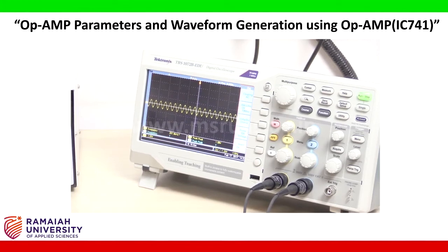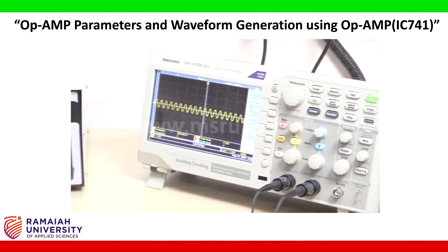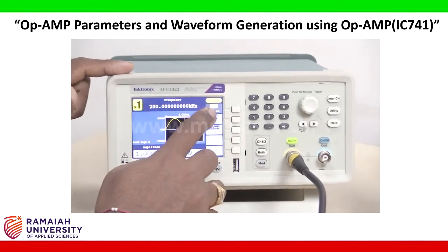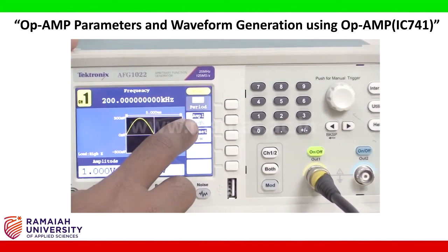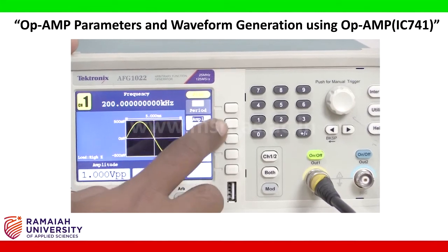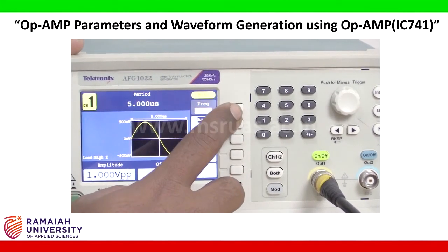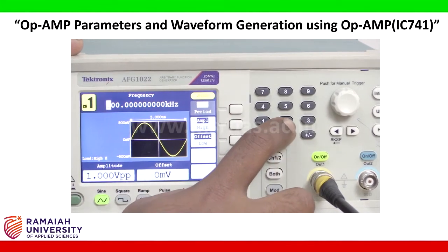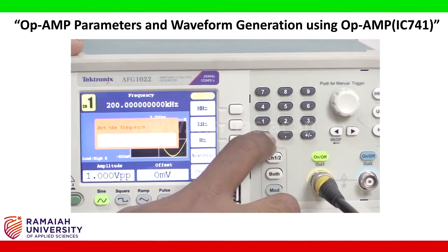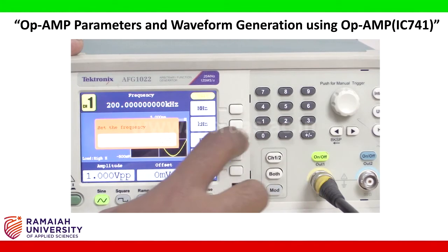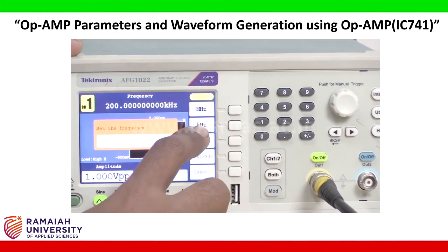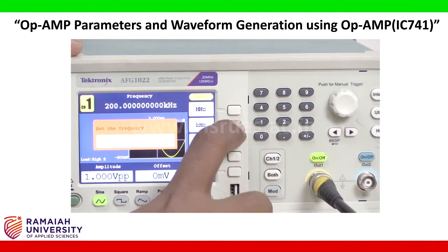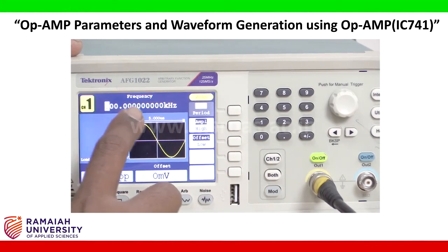Okay, you can set your frequency and voltage by using the signal generator here. So this is the frequency set and this is for amplitude setting. So you can set our frequency to 200 kilohertz, in the sense you can use these numbers 200. We have options called megahertz, kilohertz, hertz, etc. So you can click on kilohertz, it shows 200 kilohertz.